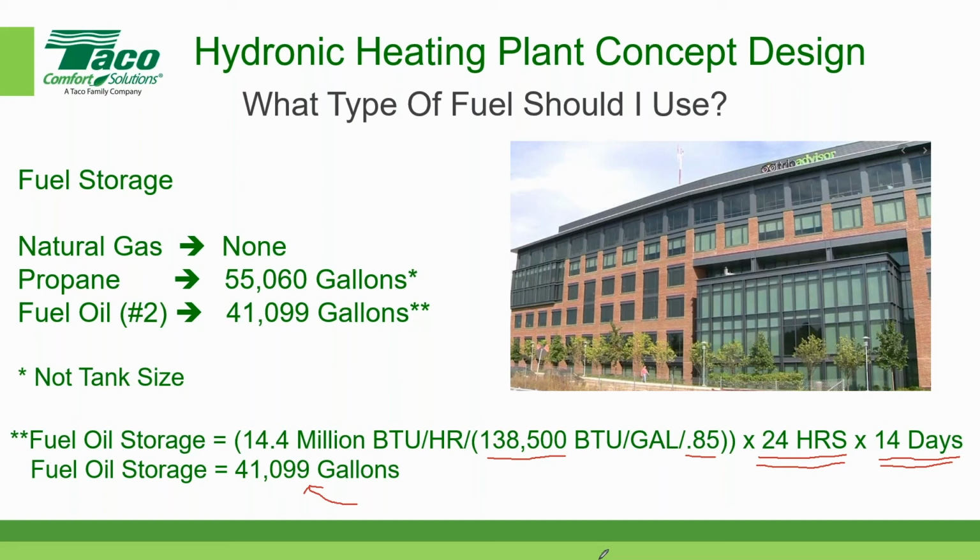Now, again, this is a simple office building. If you had a laboratory or you had a hospital, you'd probably have more stringent criteria that you would establish, and you might even want to have, instead of just a 14-day supply, a month's worth of fuel oil supply. So it depends on the functionality of the building, what the actual load is, and the type of contract that you sign with your supplier.